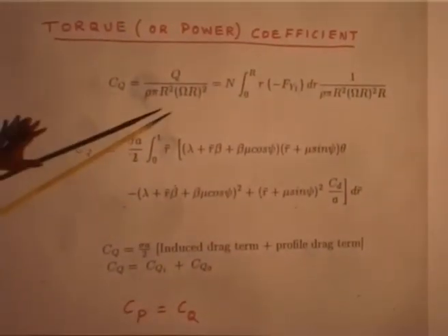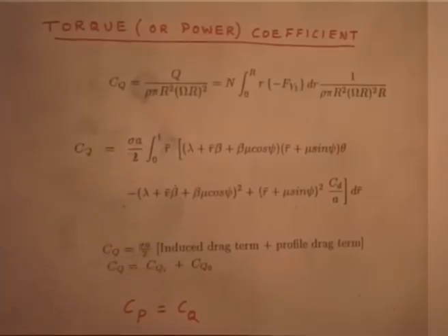Now, these are my expressions, but once I get the torque coefficient, I know the torque coefficient is the power coefficient. So, Cp equals Cq. But I have not taken the tail rotor, please understand, this is the main rotor power, main rotor torque.